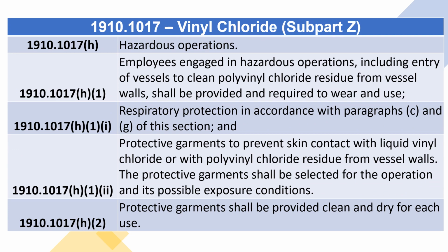1910.1017(h). Hazardous operations. 1910.1017(h)(1). Employees engaged in hazardous operations, including entry of vessels to clean polyvinyl chloride residue from vessel walls, shall be provided and required to wear and use: (i) Respiratory protection in accordance with paragraphs (c) and (g) of this section, and